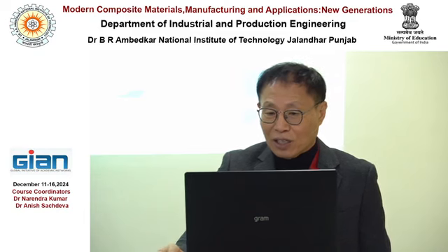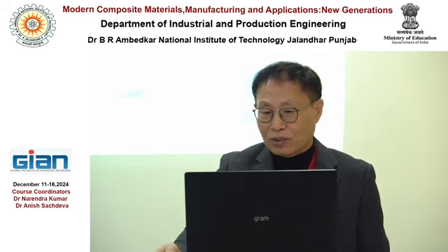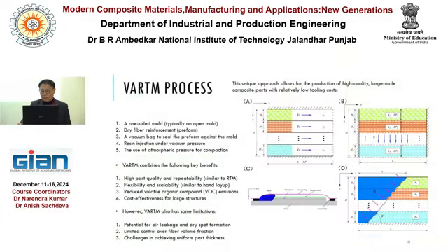So this is a kind of schematic. This kind of shape is VARTM. This pink line means the vacuum bag, and this blue one is the molten resin, and there is the resin inlet here.